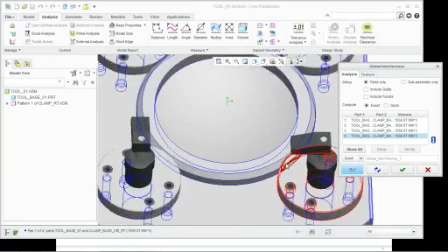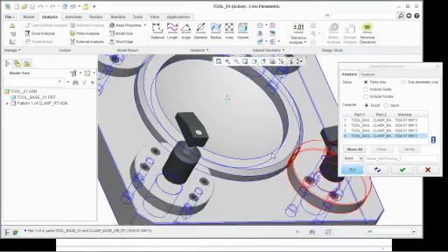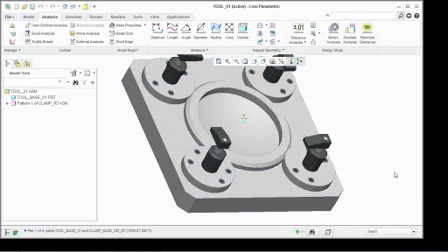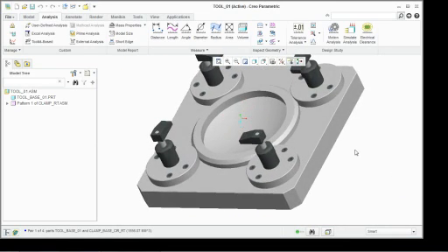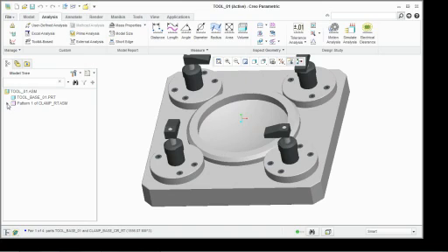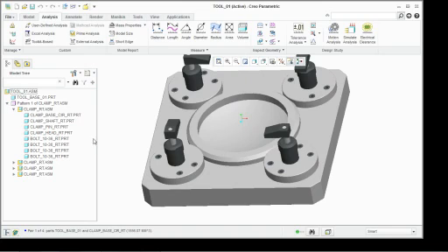If you look, you can see that that's just because the clamp base is too large of a diameter. It interferes with the existing tooling. So we're going to have to go in and change that. Well, we found another base, an off-the-shelf part made by a different manufacturer, that's a little bit different shape. Instead of going back in and redesigning this, we can just replace that specific component.